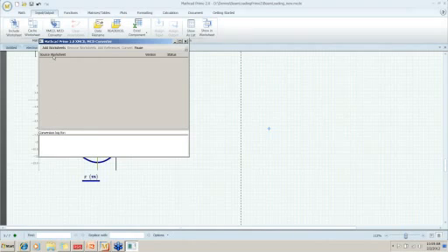Once you have your worksheets loaded into this converter, you hit the Convert button. This Convert button will be enabled. Right now it's grayed out because I don't have any worksheets loaded. But you hit the Convert button, and it'll start the process of converting the worksheets into Prime. And it's not going to overwrite your original worksheets or your original files. Those original files will remain untouched.